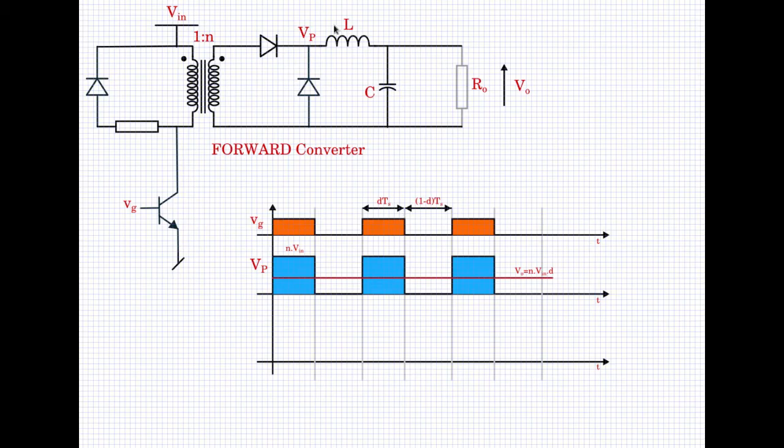So as far as the buck converter operation is concerned, it is the buck portion, that is the L and C, it is exactly the same as before. The inductor current operation is also very similar. We will revisit that later on, but there are some other important waveforms that you need to look at. The primary current that is flowing through the switch, and the portion of the current that is freewheeling when the switch is off. This is actually the core reset current, the current that will reset the flux within the core and makes it ready for operation in the next switching cycle.